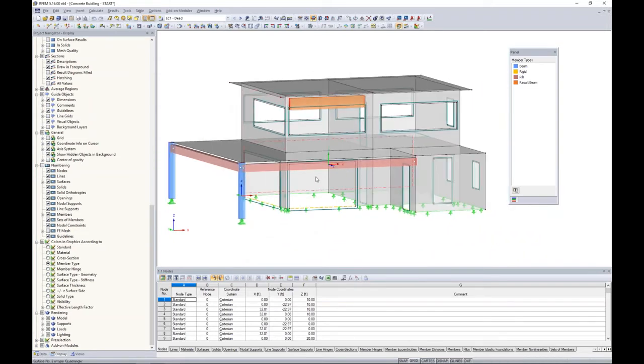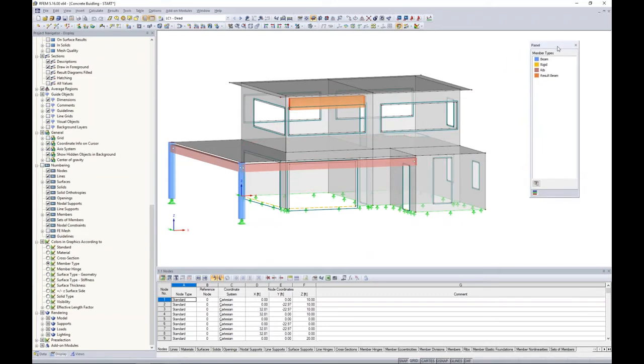Okay, so now that we have covered the basics of the surface and beam members, I want to talk about the I cracked. Now the I cracked is just simply the gross moment of inertia multiplied by a factor, and this comes directly from Table 6.6.3.1.1(a) within the ACI. The ACI requires us to take into consideration cracked section properties.